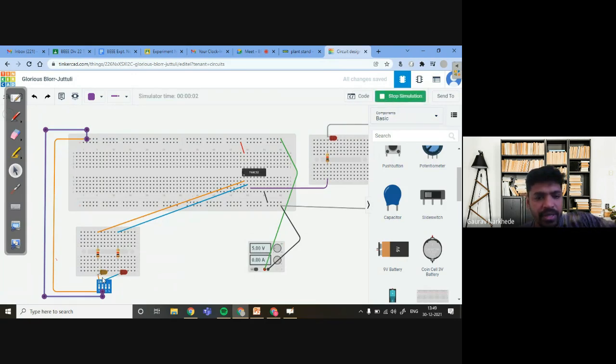Okay, so again there is a problem, right? So this is the power supply, this is connected to, okay, ground is not connected properly. Can you see this thing? This ground is not connected properly. This is supposed to be connected at this line. Okay, so the IC did not get ground, that's why it was getting busted. Now again we will start simulating.